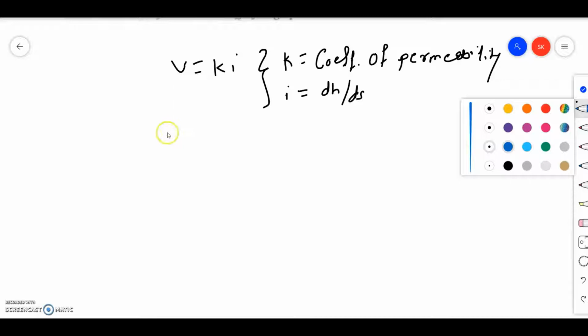Generally when we see flow through an open channel, if the flow is transient there is a particular limit, for turbulent there is a different one, and for laminar it is different. But in case of a porous medium, it should be laminar, and limited to unity, which means 1.